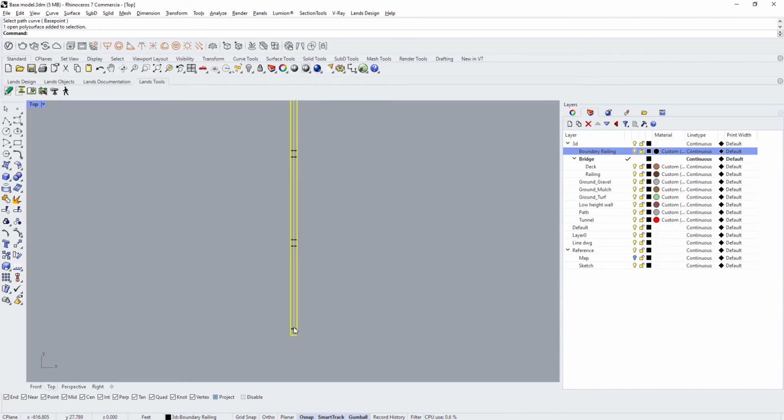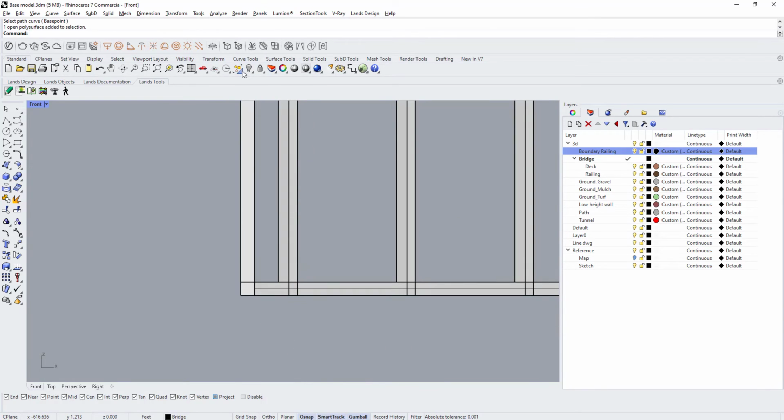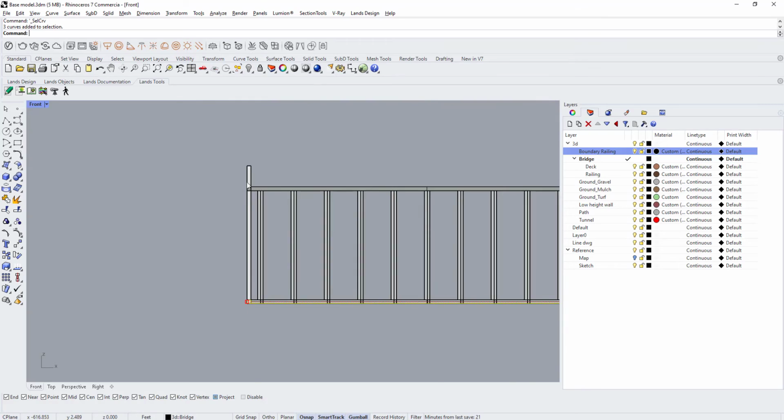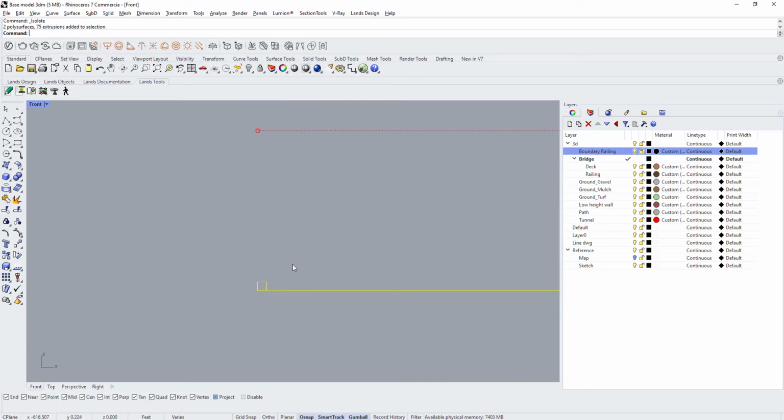For some reason I can't seem to find it, so I can drop that again, or I could isolate that curve and that element like that, and I will delete that one now. So I will go to the top, array curve, I will select that object, and then select that curve and change the number into something lesser, like 50 or so.